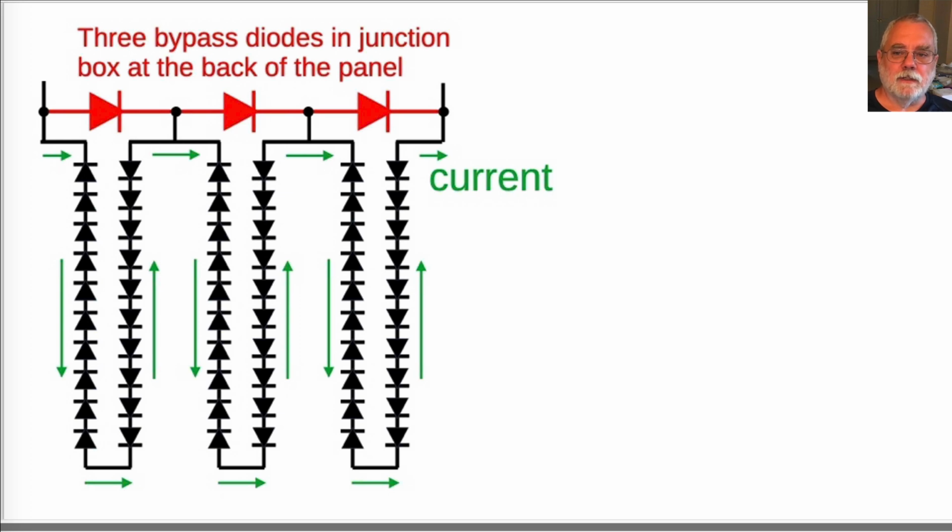The cabling for the installer connects only to the outer two terminals. A solar system salesperson might not know about the bypass diodes. The bypass diodes are useful regardless of how panels are connected together: string inverter, microinverters, or DC power optimizers, as we shall see now. But beware, supposedly some panels do not come with bypass diodes.